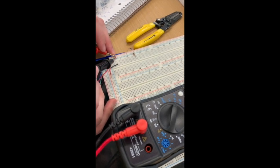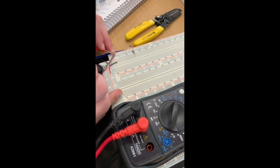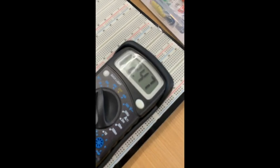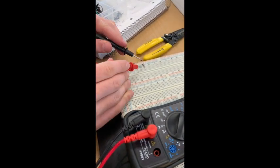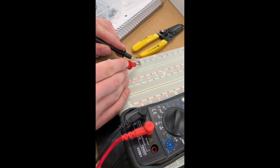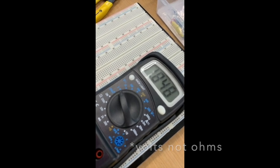The voltage from the input to the ground is about 2.5 volts, which is the input, and across the resistor 1.84 volts. So you see that the voltage drop is about 0.7 across the diode.